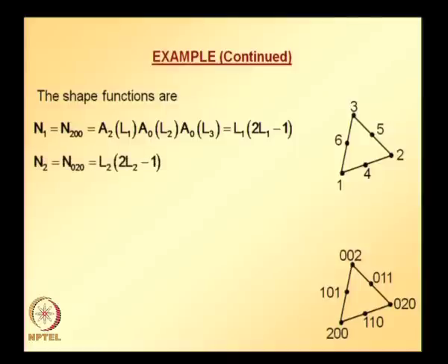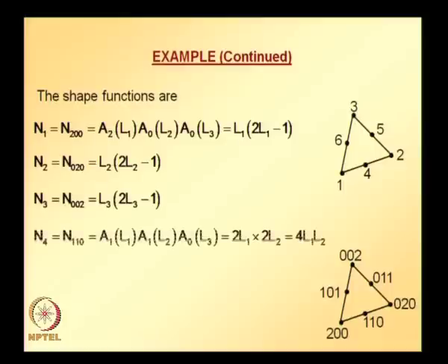Similarly, shape function for node 2, node 3 and node 4, node 5 and node 6. With appropriate change of variables, all integrations and differentiations necessary for developing finite element equations can be carried out in the natural coordinates.